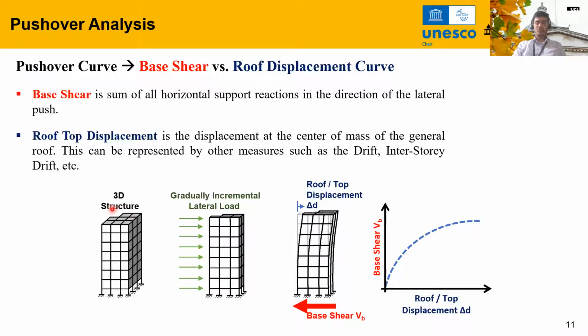Here this just shows a snapshot of what the pushover analysis looks like. We model the building 3D structure. We gradually apply a monotonically increasing load pattern on the structure. We record the base shear versus the top displacement. We plot the results and then we get the pushover curve.